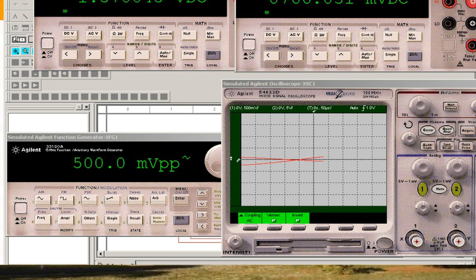It's 700 millivolts, that's 0.7 volts. So it's acting like a silicon diode, I think. Okay, that looks much better. See, that capacitor, I think it was doing something not good.